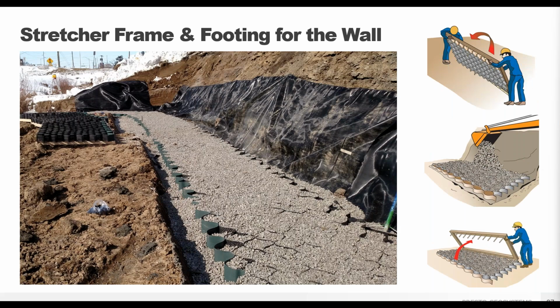Once the section with frame is in place, infill can be placed and then the stretcher frame lifted away. Here we see the frames lifted away and reloaded, far left, getting ready for the next layer. Don't forget to compact each layer.